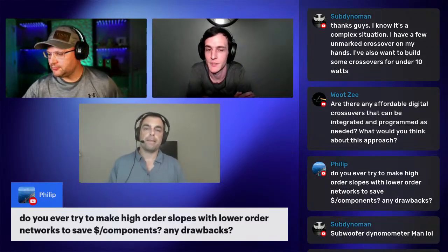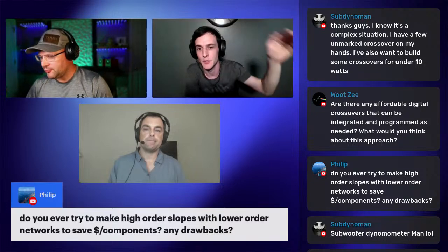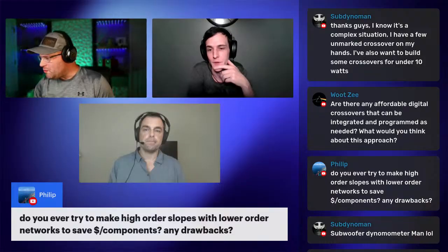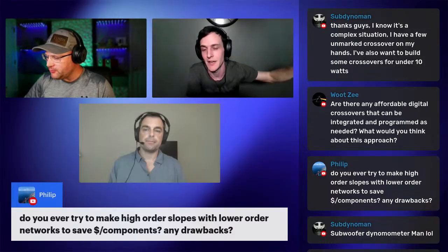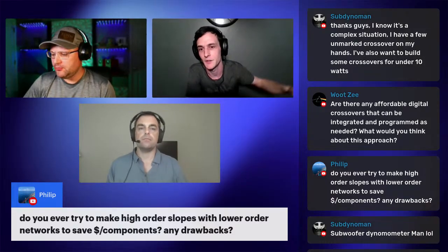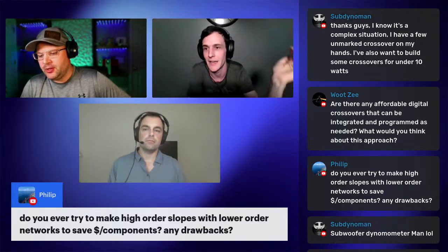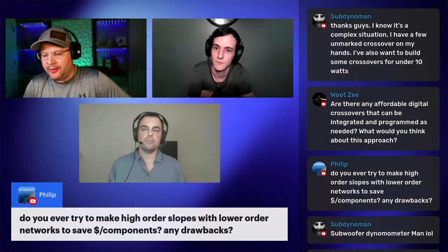The situation Ryan was describing is where the tweeter naturally begins to roll off or climb up, depending on which direction you're looking at it. And so if you're wanting to cross it, let's say you're designing a three-way and you're going to cross it way higher, you might need a higher order filter in order to roll it off more quickly when you're not using that natural roll off.